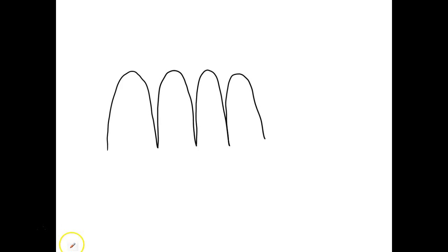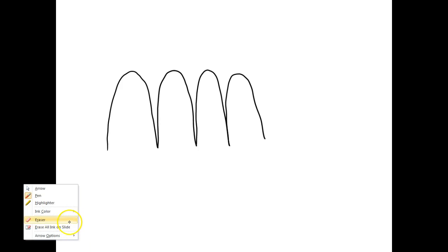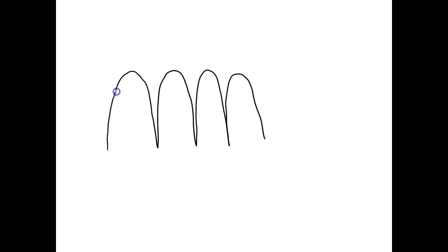We're going to filter. Okay, so now what we got to do is keep these pulses from getting down into my regulator. So we come up here and we filter this, then we're going to end up with something like that, right? You understand? But if it's a 12 volt regulator, if these valleys right here drop below 12 volts, then our regulator can't regulate, right? Because what we'll end up on our DC is something like this. And we don't want that to happen. So what determines the size of that slope right there?